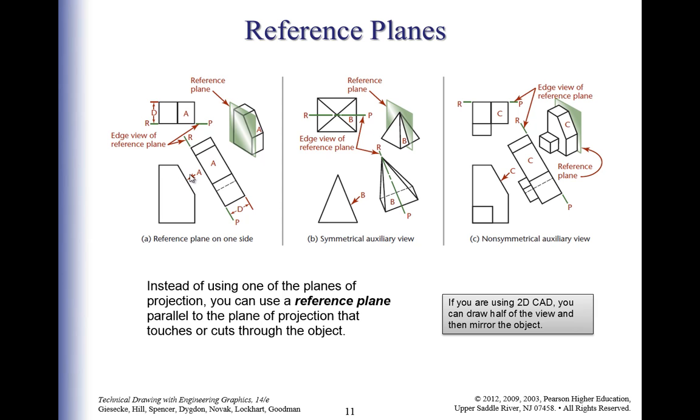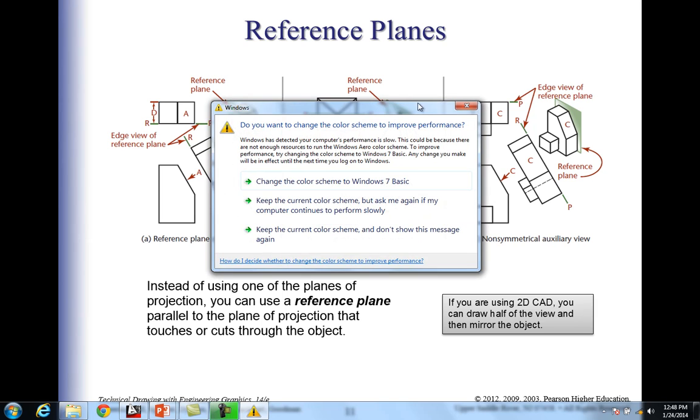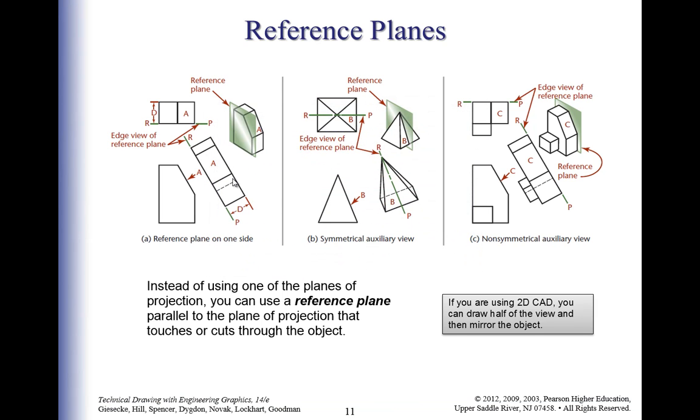And then of course it just folds out, and you get this flat distance that shows the true shape of this. All you got to do is come up here off this reference plane, and D is your distance. You just get your distance in, and then like we did earlier, you project your lines up, and they hit perpendicular, and then there's your object.